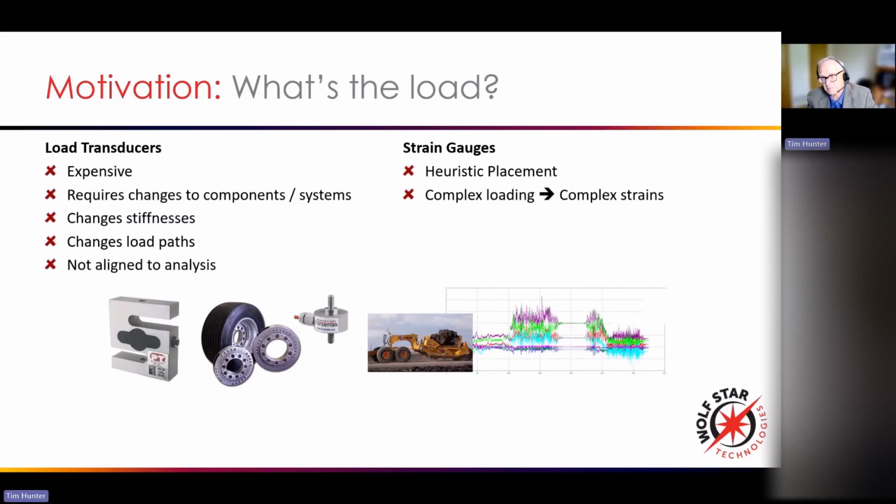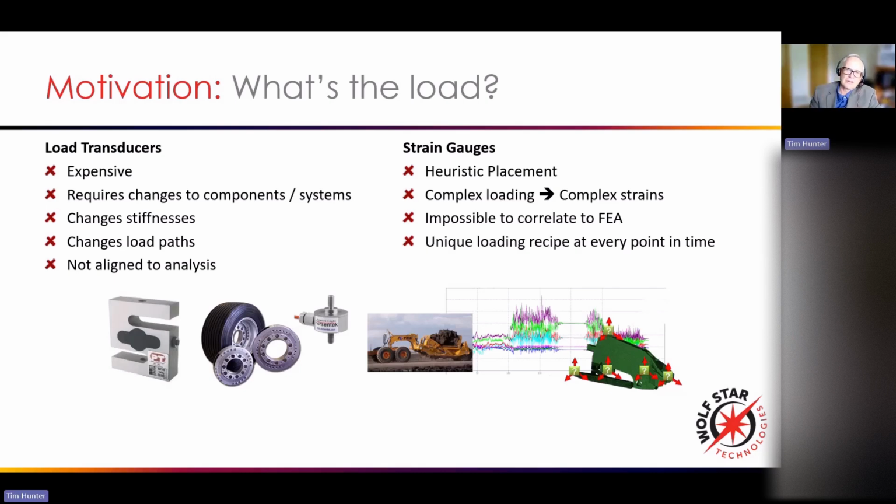And so typically what will happen is you'll pick one or two channels of data at one or two points in time, and you'll work for days, if not weeks, just getting those two areas to light up qualitatively the same way. I'm not talking quantitatively, I'm just talking qualitatively the same way, and say, yes, that's my load case. And then you go in and then you start redesigning your part with these new loads. And then the next time you get to your proving grounds with your new parts, you found out you've got the same mistake and you're doing it all over again.